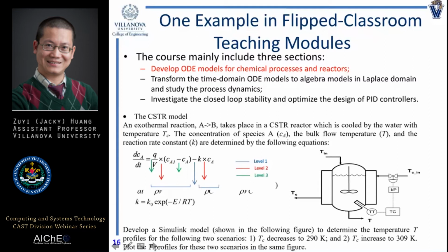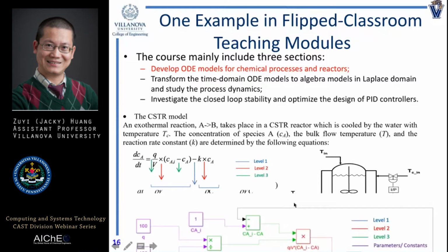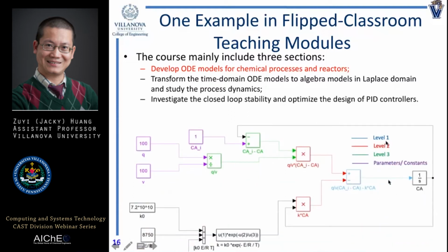For example, level 1 is the minus sign, and after that, level 2 is the product, and then another one, so that we can represent the ODE in different levels. Just like how we can break the ODE into different modules, and then we can use those modules that are available from Simulink to build the model.